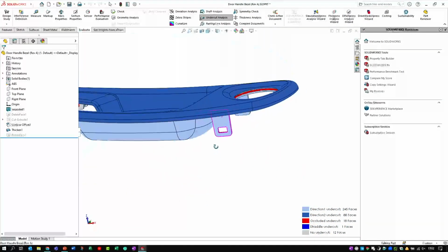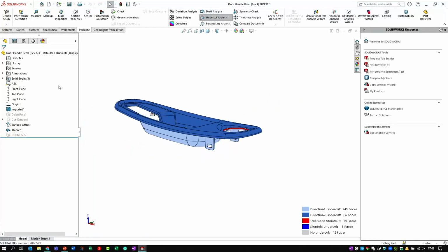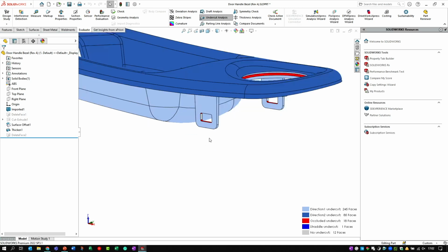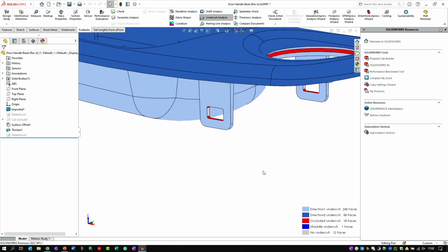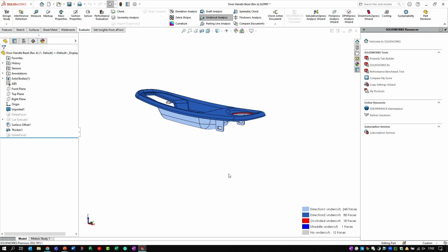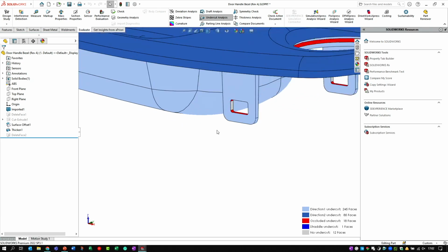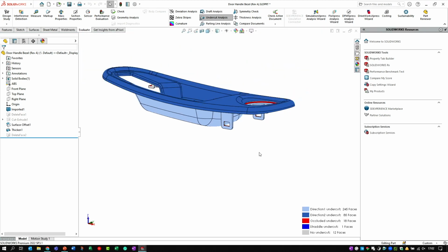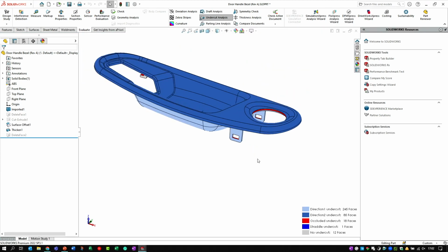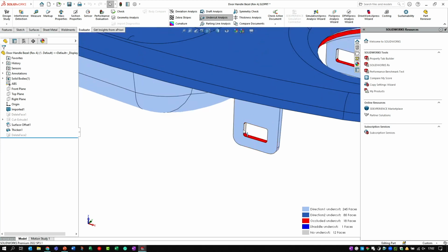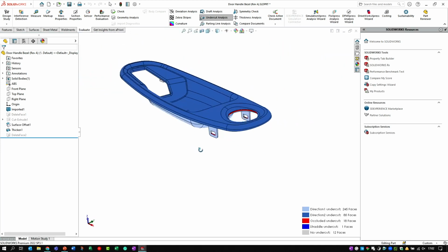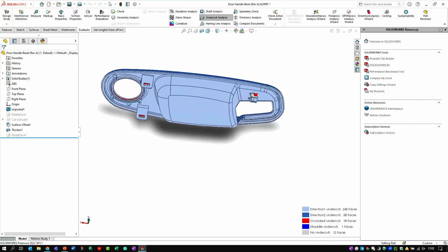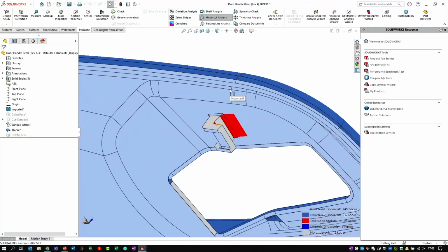So if you imagine the tool is split across here, I've got one half in the cavity, the other half in the core. How am I going to achieve this? Because the motion of the tool coming apart is not going to allow me to do that unless I've got a side action to achieve those holes. So that's going to be way more expense just to do that. So if I can avoid that somehow, then that's going to save me a lot of hassle.